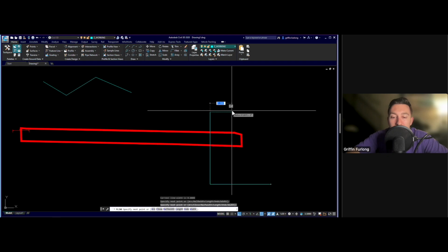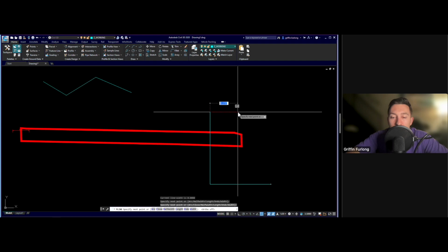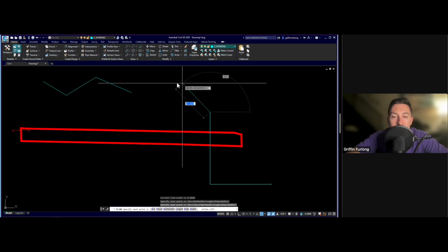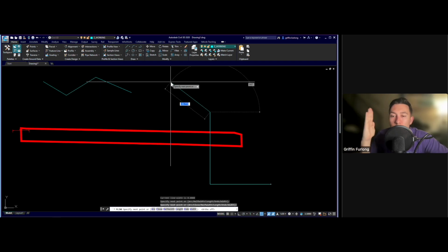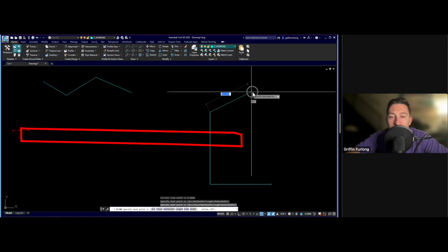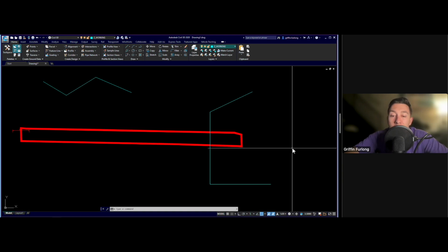And again, you can toggle it off by pressing F8, or you can go down to the little icon, and now it's not necessarily a perfectly straight north, south, east, west line. I can go in whatever direction I want here. So that's a critical one that I would keep in your handbook. You're going to be toggling F8 all the time. Another critical one that I want to show you guys is these snaps.